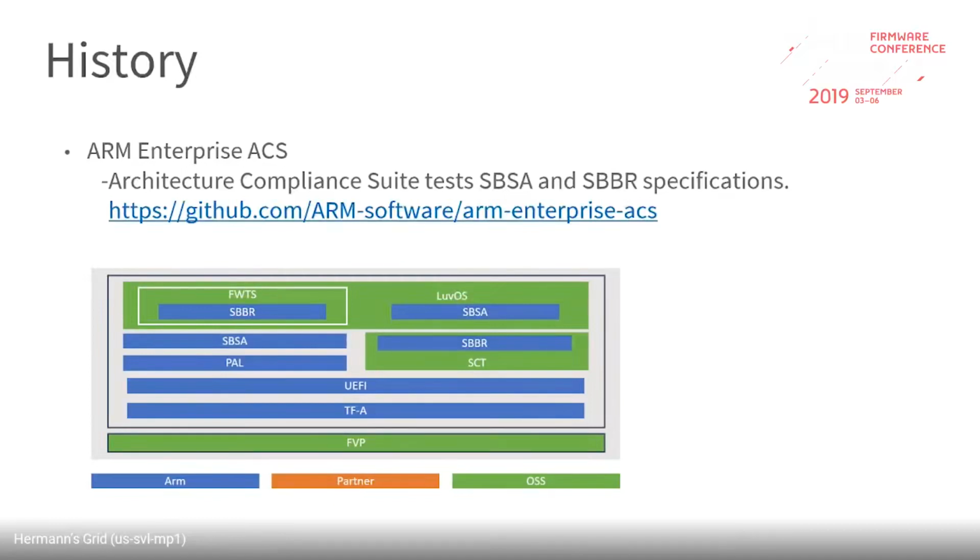This is built on top of the Linux UEFI validation operating system. It basically has the SBBR set of tests, which is part of the UEFI self-certification tests, as well as a SBSA component, which is a UEFI shell application that runs and tests the SBSA portion of the requirements.